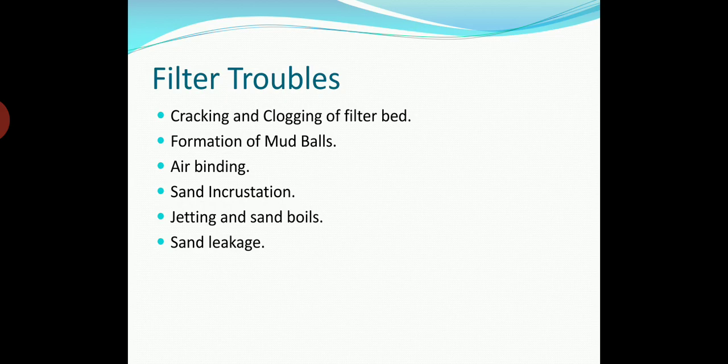Mud may accumulate on the sand surface to form a dense mat. During washing, there may be some lateral pressure between the points where the water breaks through and the sticky mud is pushed into lumps or balls of the size of a green pea, up to 2 to 5 centimeters or more in diameter.